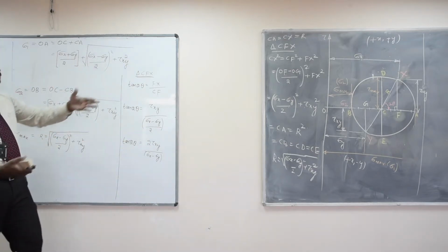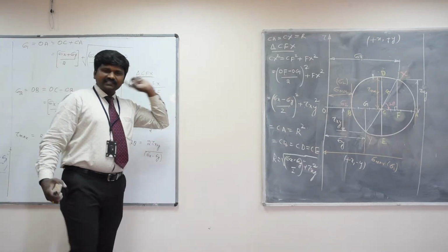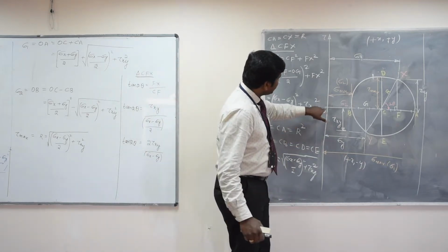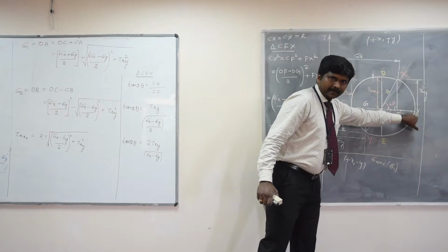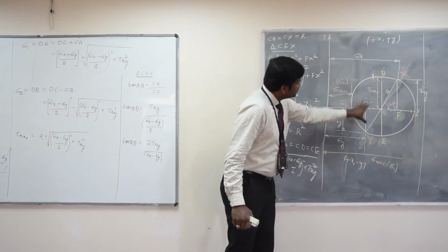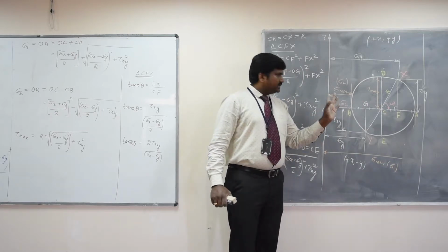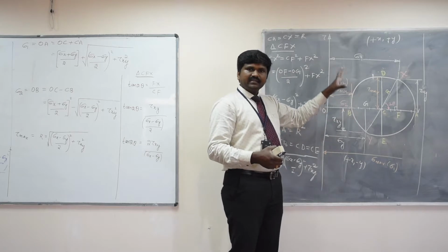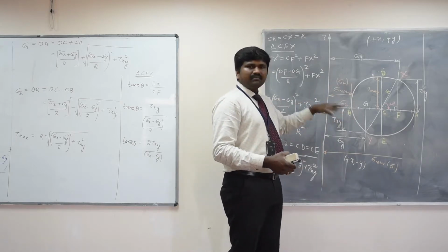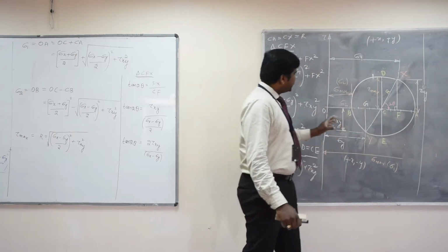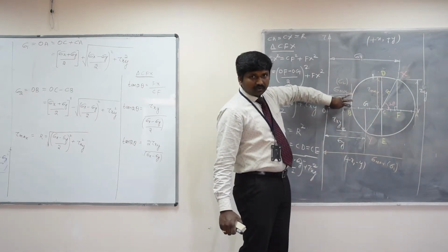Now from the Mohr circle diagram, how do we find out the maximum principal stress? I have already told you the maximum principal stress is the distance from O to A. The minimum principal stress is the distance from O to B. From this geometry, we should be able to calculate them. After you construct this in a graph sheet, you can just directly measure the distance O to A. That's all. To find the minimum principal stress, just measure the distance O to B.